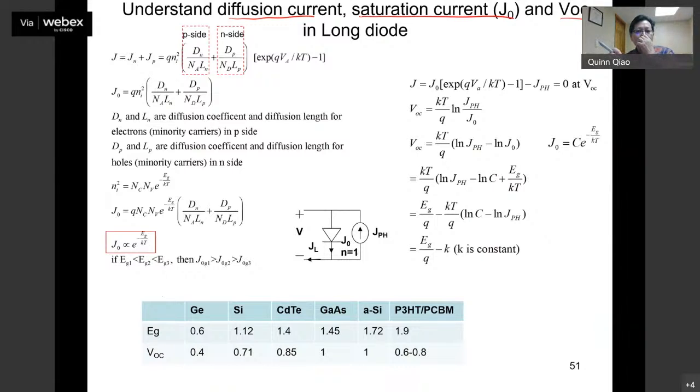In this slide, okay? First, as you see, we already see these equations, right? This part, total is what? Called J0, right? That's called J0. It is the saturation current, okay? And then this part, especially when you bias, right? That's how much extra current you can get, okay? So there's a definition here. This is J0. So J0 depends on what? It depends on this Ni square, intrinsic carrier density, right? For silicon, it's 10 to the power 10, okay?